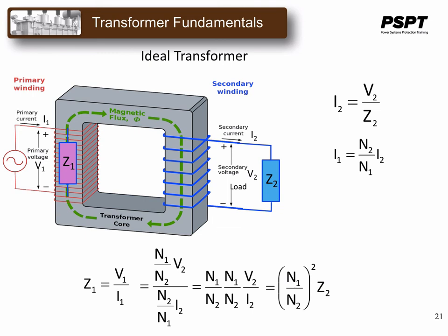This is characteristic of a transformer, and it becomes very handy for impedance matching and the like, which you have to do sometimes in audio circuits. However, if you are going to see what the impedance reflected to the primary of a transformer is, you have to use the square of the turns ratio.